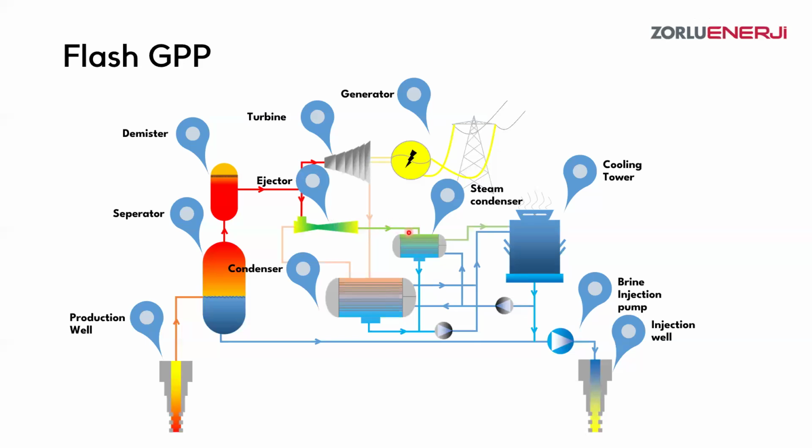And in here again, because you use steam in the system, you mixed your steam for creating the vacuum with the vacuumed NCG gas, and again you are condensing your steam in here, and after that, with the little pressure that you have in here, you are emitting that gas into the atmosphere. And in here we have a cooling tower.